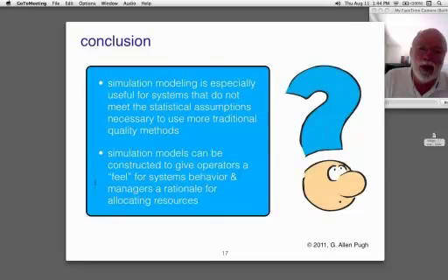As far as selective assembly, there's been a lot of work published, a considerable chunk of it by me a long time ago. It seems to me that most of the follow-up and most of the questions have come in from areas of the world where production capabilities are not that great and where labor costs are small enough they can actually manually inspect every component. But now with automated inspection techniques, selective assembly can become a viable technique again. But again, you should only consider using it when you really don't have very good production techniques or methods relative to specifications. Examples might include some very difficult manufacturing things that go into satellites, which have incredibly difficult specifications to meet, and it simply requires a lot of oversight.